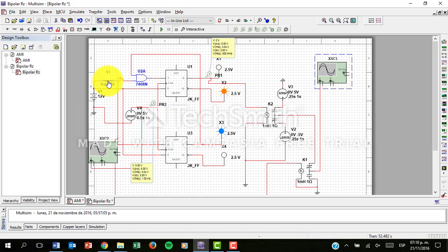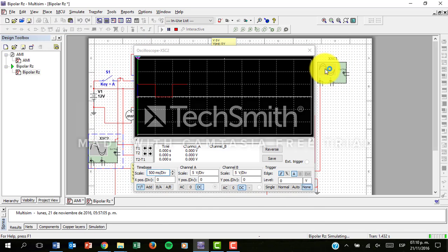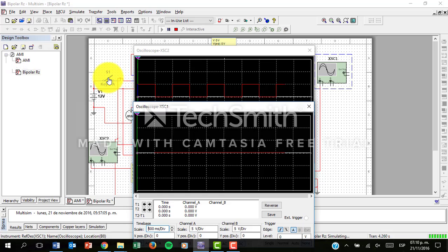And in here we can also check that we have a 0. When we have this 0 state, we have the first state, which is going to be half the pulse. I'm going to stop the simulation here. At each pulse of the main clock, we have half of the pulse, one in positive, one in negative, one in positive, one in negative, and so on. If we also change this one to 0, the states go to 0. And that's basically how the bipolar RC and the AMI line coding work.